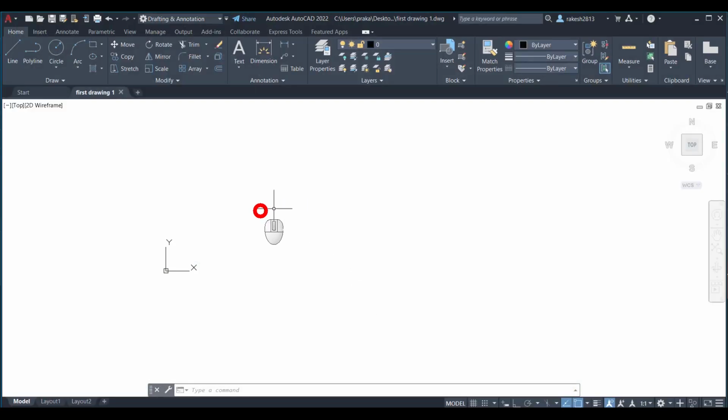Now, so this, I told you, this is your workspace. This white space is called your workspace, and this is an infinite space. Now I'm going to confine my drawing to a certain region. For that I'm going to draw a box. That box I'm going to draw an A4 size sheet size, that is 210 by 297, 210 millimeters into 297 millimeters. So let me set the units.